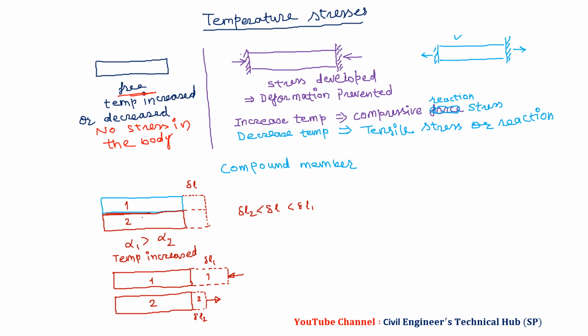And therefore, in this, you can see the summation of Fx equals 0, so both forces should be P. Therefore, we have compression in this one and tension in this one when temperature is increased.